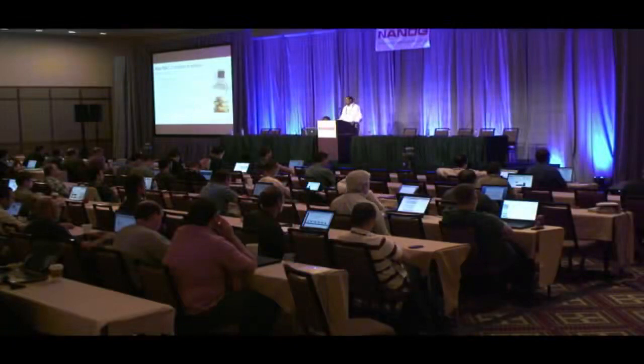On the MAC side, 3.1 is mainly a new PHY, right? It's a new OFDM PHY, and the MAC essentially has updates to support everything the new PHY has. So it's a new OFDM. How do you range on that? How do you figure out the downstream channel parameters? How do you figure out the upstream channel parameters? The MAC has changes to support the new PHY. So, ranging, probing,